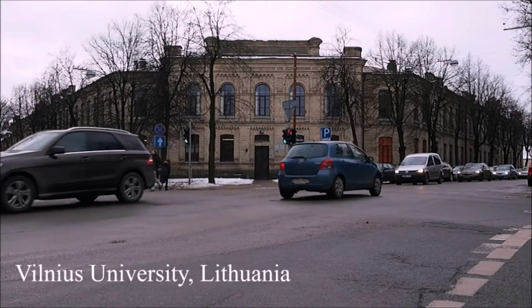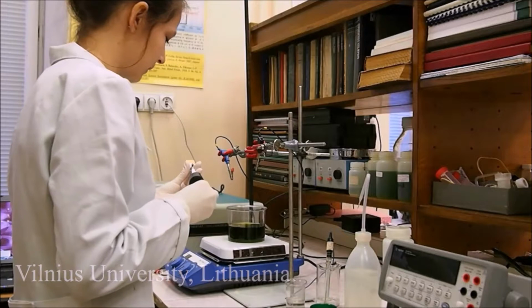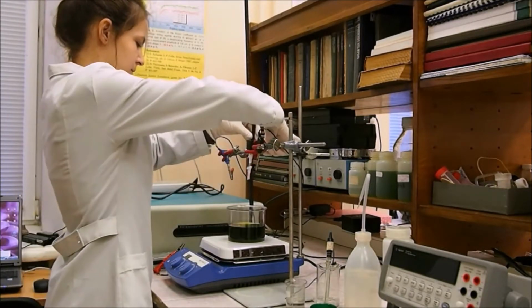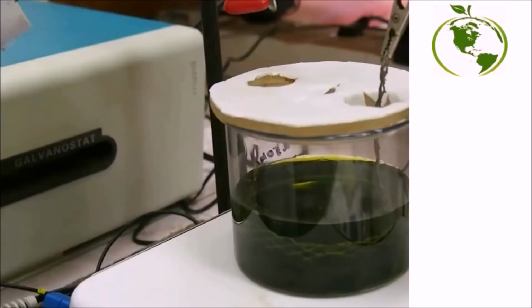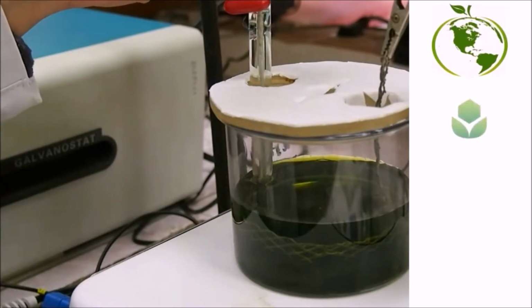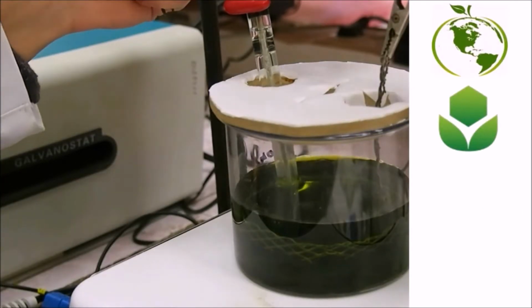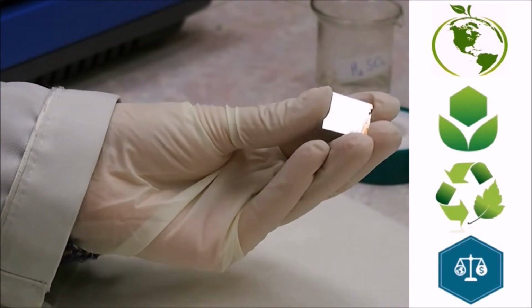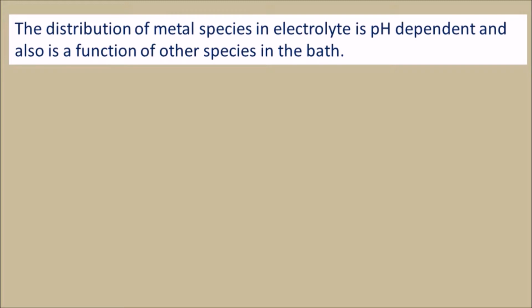Here at Vilnius University in Lithuania, we are working on green electrochemical synthesis of iron-tungsten alloys for target applications, while avoiding the use of critical raw materials and hazardous chemicals in the electrolytic bath, minimizing waste and maximizing the economic viability of the process. The overall distribution of metal species in electrolyte is pH dependent and also a function of other species in the bath.